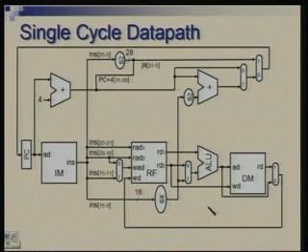So, let us take this as a starting point, which is a single cycle design, and in this we will see what changes are required if we have to share these resources, and we know that we are going to do a multi-cycle design. So, each major action would be done in a separate clock cycle.